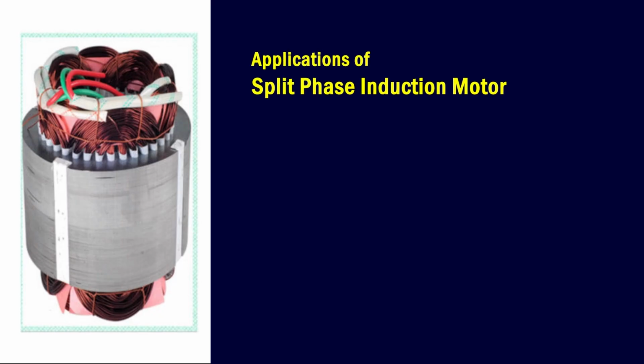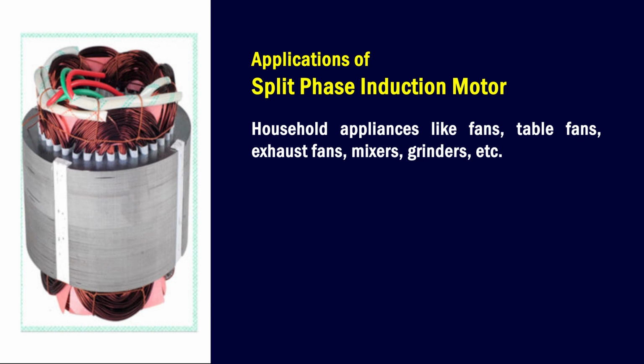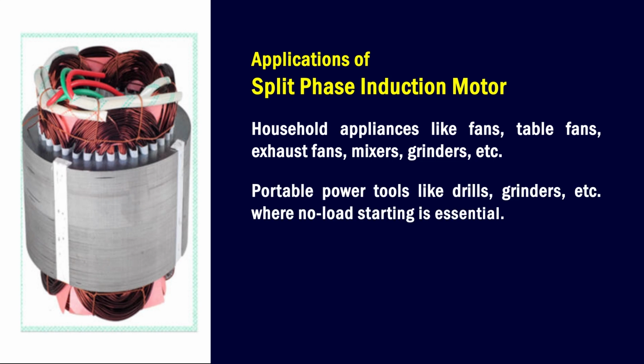Now let us discuss the applications of the split phase resistance start induction motor. Household appliances like fans, table fans, exhaust fans, mixer grinders, etc. use this type of motor. The portable power tools like drillers or grinders, etc., where no load starting is essential.